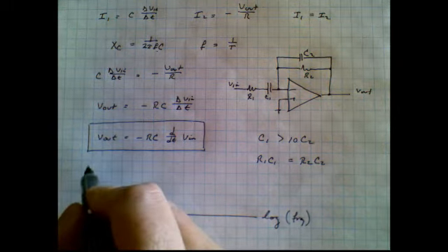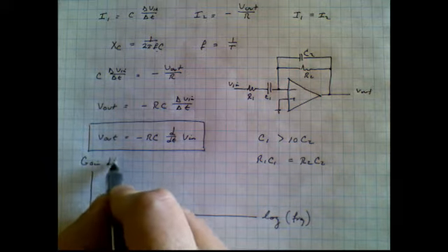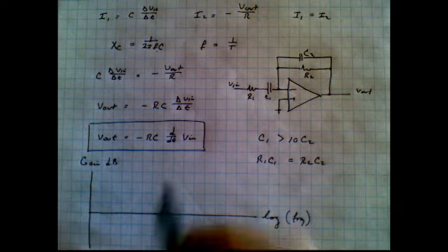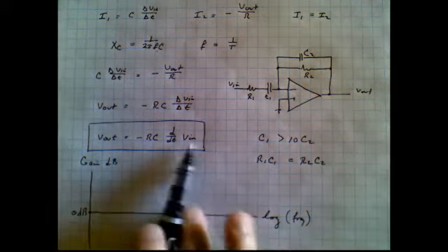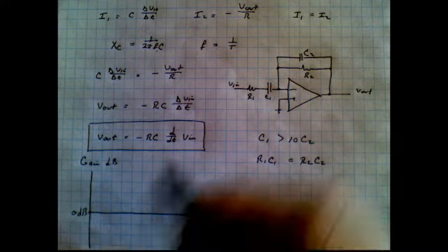And in this direction, it's the gain in dBs, decibels, which is also a logarithmic scale. Now, the beauty of using logarithmic scales is that when we plot functions of this type with exponential components like RCs, time constants, they turn out to be straight lines.